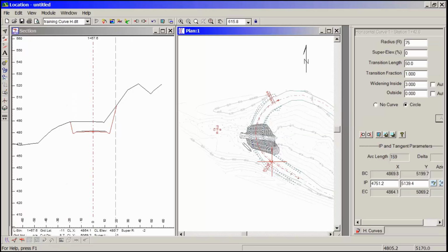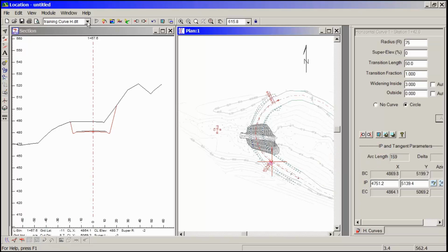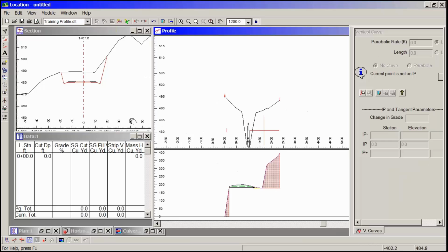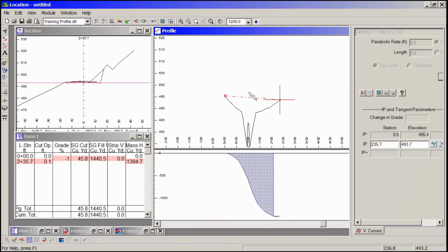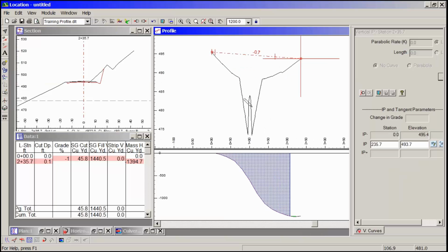There. Now I've got to do some vertical design, because right now basically my center line is sitting on top of the ground, and I don't want that. I want to have a nice vertical curve in there. Retrieve a screen layout for profile design. Left click once. It's a short segment of road. As you can see, there's that culvert in there, that arch.